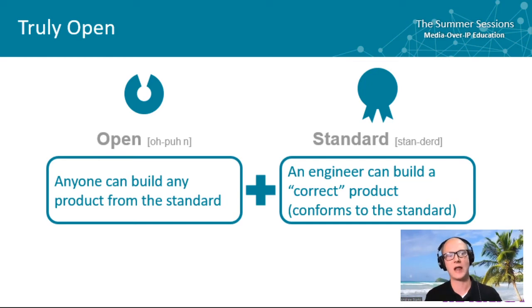There are codecs that have relatively the same latency, but there's no codec out there that I'm aware of that has that balance of power efficiency, implementation efficiency, and latency, and everything that goes into being a viable, best choice solution for something that's a transport, right? You don't want something that is burning 4 or 10 watts of power just to get 1080p video over the network, but has great video quality. It doesn't work in transport when you have to scale it so high, right?